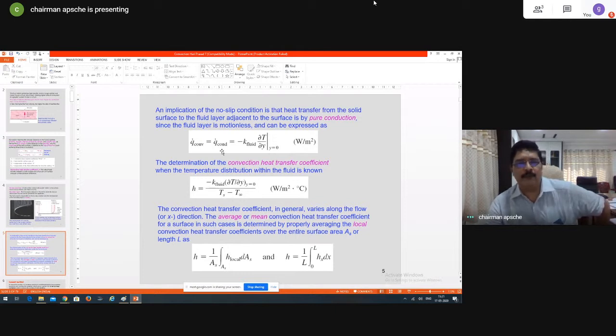So it is the fluid conduction that happens, and because of a temperature difference, there is temperature variation in the y direction. So convection is equal to conduction at y equal to 0, and the same heat is subsequently convected with the different molecules on top at various y distances. Therefore, if you have to define the heat transfer coefficient, from here it is conduction heat transfer.